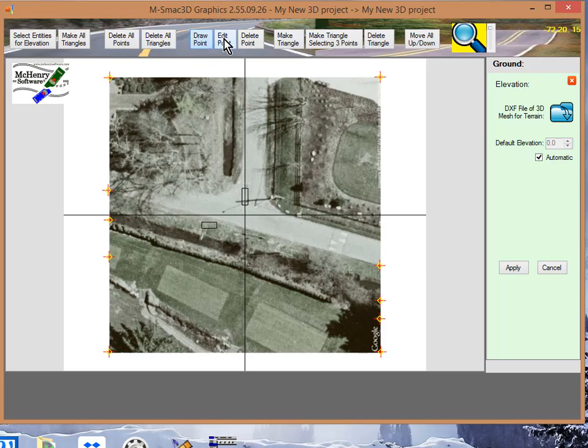The second thing you could do is go edit. And so plus is up, minus is down. So we're going ahead and put in here minus 5 feet at the edge to run down from the road. And then we'll put here minus 3 feet maybe to make it a slight upslope before the larger upslope. Make this minus 3.